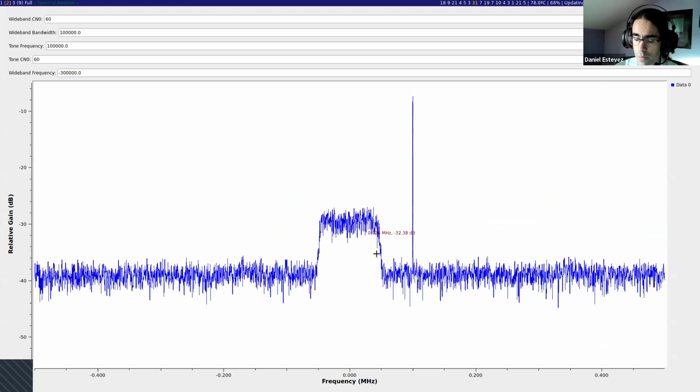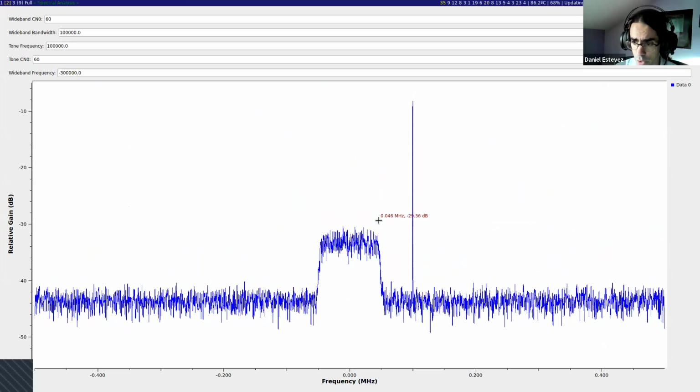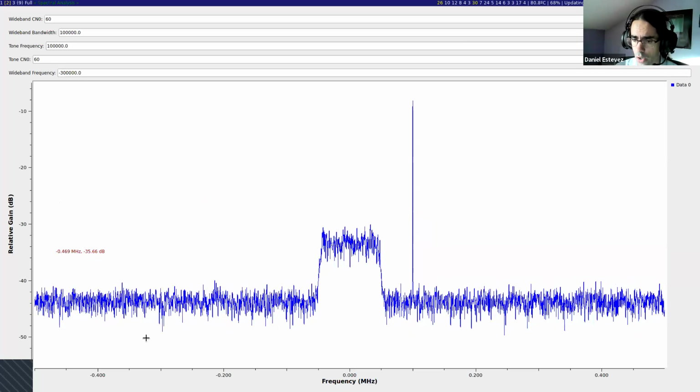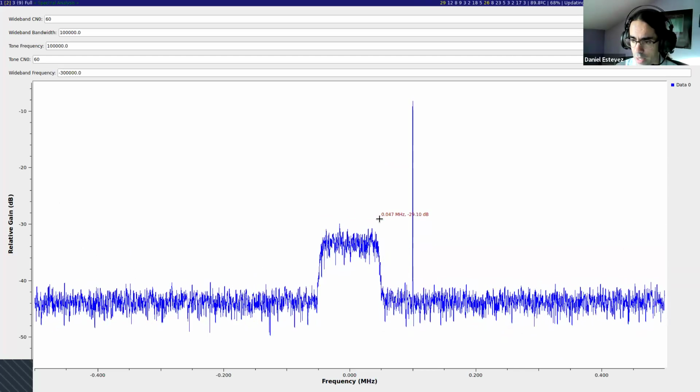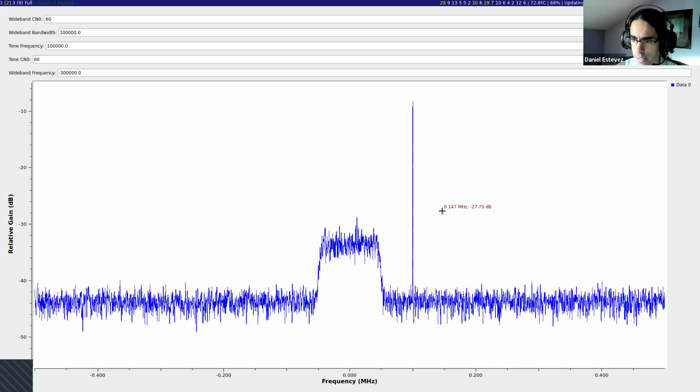And if I do not use this multiplication block, let me do it like this, then it will be in the center of the spectrum. So basically we had something that was this as the noise source output, and we are putting this as the center of our complete spectrum. And this is 1/10 of the spectrum. The remaining 9/10 is zeros.